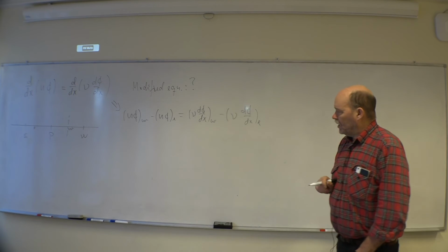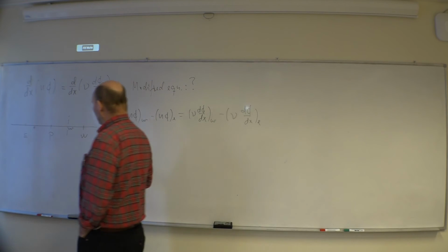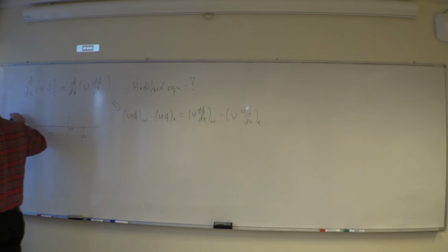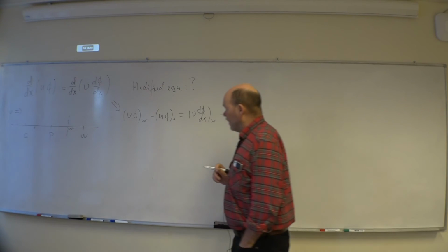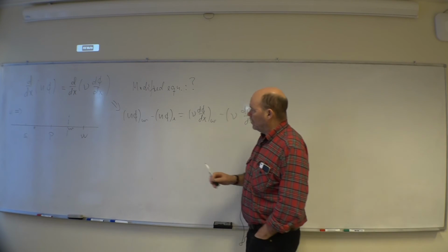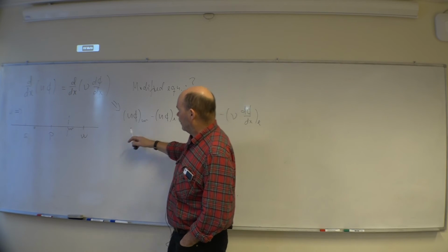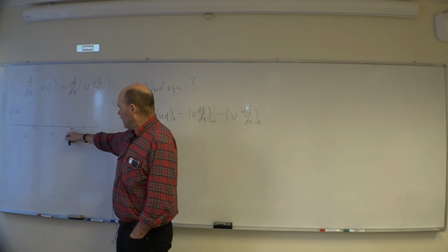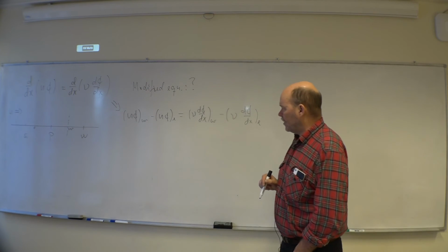And then we now choose an upwind scheme, saying my u is positive, going to the right. So the value here at the point west is actually coming from the center point itself.